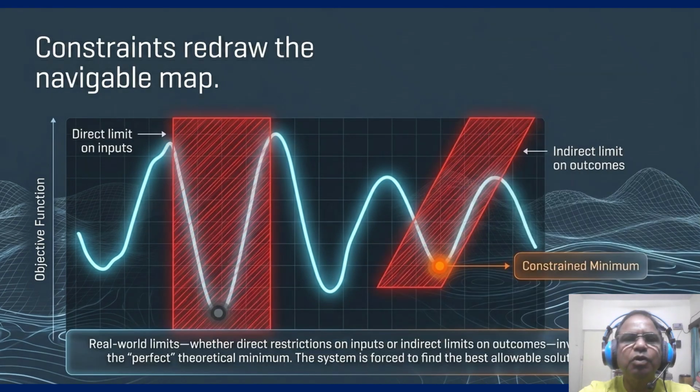Coming to our next slide. In theory, the best point may lie outside the actual operating limit. That is why the constraints are very important. For example, blower capacity, flame temperature, slag chemistry, top gas temperature and sulfur limit can all restrict the final solution.